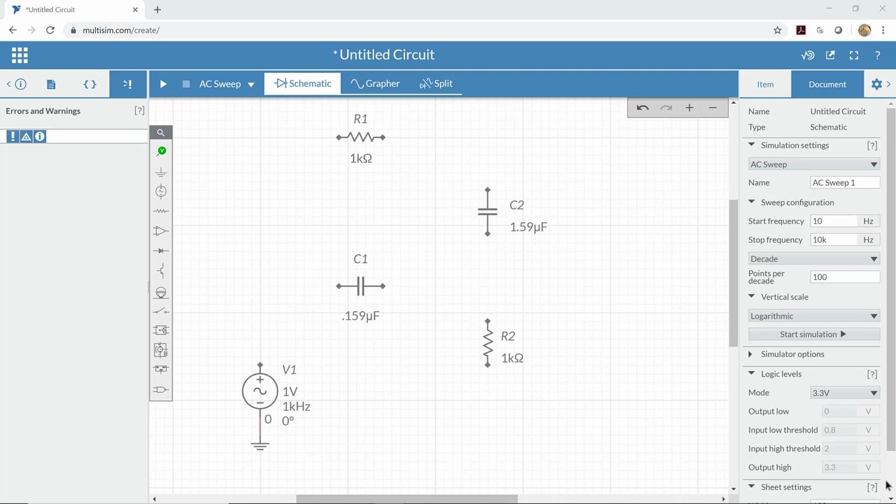Remember, last time the low-pass filter had its cutoff frequency at 1,000. So now the low-pass filter has the cutoff frequency of 100 hertz, and the high-pass filter has a cutoff frequency of 1,000 hertz. Okay, so I've got the components that we need here. The calculations are just the same that we've already done, so I won't redo those, but you could do them again if you needed to choose different cutoff frequencies.